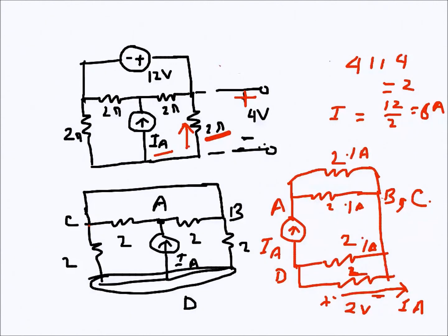So we can see that there are four paths here. So this current goes this way, and then 2 ohms here, 2 ohms here, 2 ohms, and 2 ohms resistance. So we need to have 1 ampere in this direction. So if we assume the current is going that way, this current is negative. Whatever current is coming out of here is split in half here, and then they become the same current here, and then again split in half and come back.